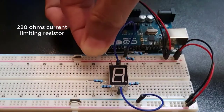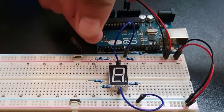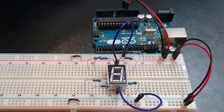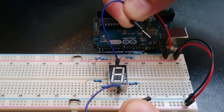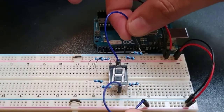I'll be connecting a 220 ohm current limiting resistor to each individual segment. Now, a huge question is, how do you know if what you have is a common anode or a common cathode 7-segment display? Unlike with a single LED, wherein you can easily spot the anode and the cathode pins, in a 7-segment display, we have to test it.